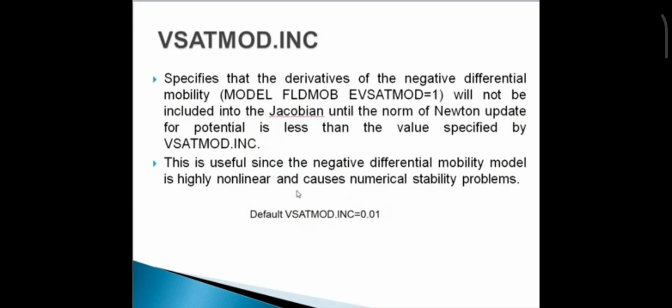Next is setting the vsatmod.inc in the method statement. It specifies that the derivatives of the negative differential mobility will not be included in the Jacobian until the norm of the Newton update for potential is less than the value specified by vsatmod.inc. The default for this parameter is equal to 1.